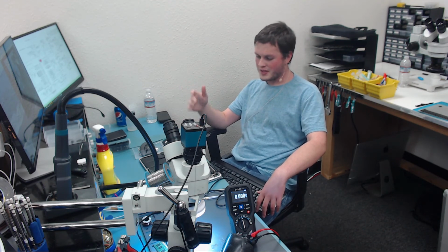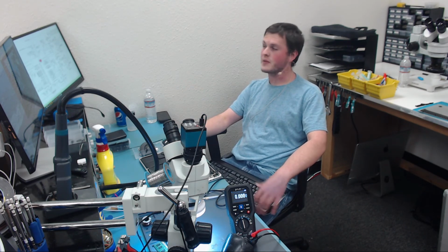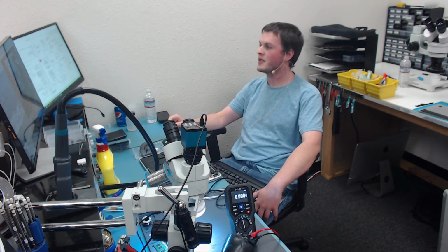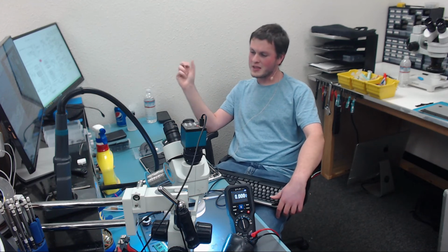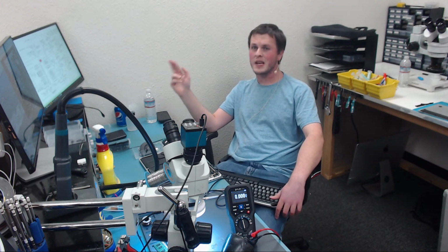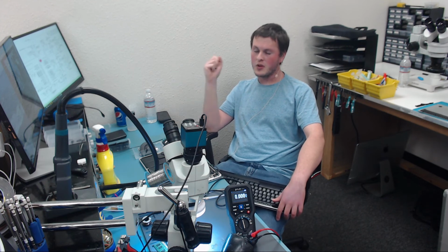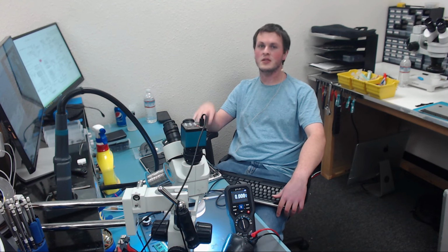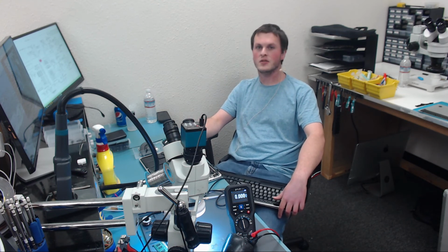These GT650Ms, whatever these are, almost never fail. It is almost always the cracked joints on U8900. Sometimes you'll get traces around them that'll crack. It happens. Rarely the chip is dead. I've seen it a couple times though, but most often it's just those solder joints that break. So please stop killing these. Please stop heat gunning these graphics chips.